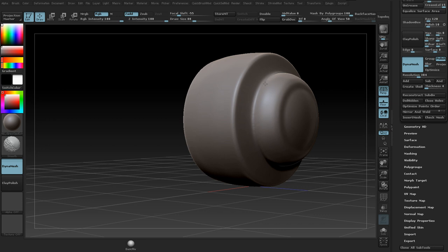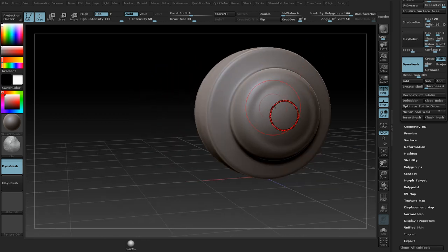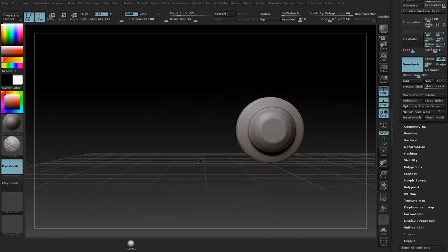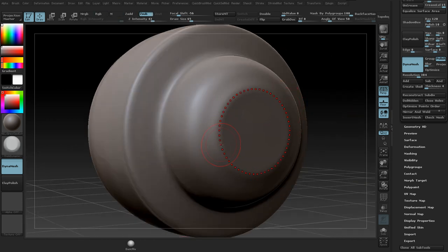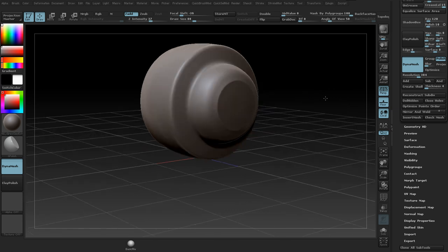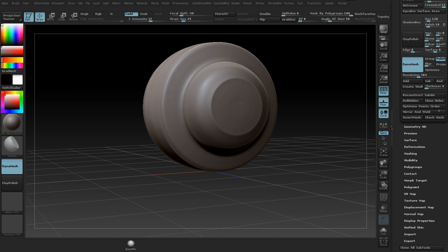But basically what I'm trying to do is make sure that there is the middle portion, which is going to be the buffer area. You'll see it when you actually apply the brush. But there's going to be a huge buffer area in a lot of the brushes to where when you're drawing it negatively onto the shape, it's just to make sure that you're cutting away enough of the shape. So the largest radius on this piece is buffer, basically. I'm just using the H polish brush, a lot of the trim dynamic brush, a lot of the Damien standard brush, and that's pretty much it.